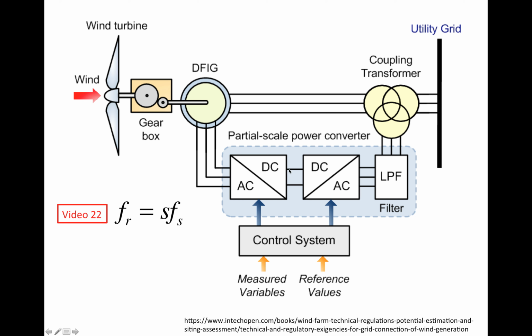right? Now you see just 2 wires coming out of this block. One is positive, the other one is negative. It's just like a battery. A battery has just two terminals, right? The DC power coming out of this block has just 2 wires. And then this block converts the DC power coming off the previous block into AC power with the correct frequency, the grid frequency, which is 60 Hertz in the US and 50 Hertz everywhere else, right?